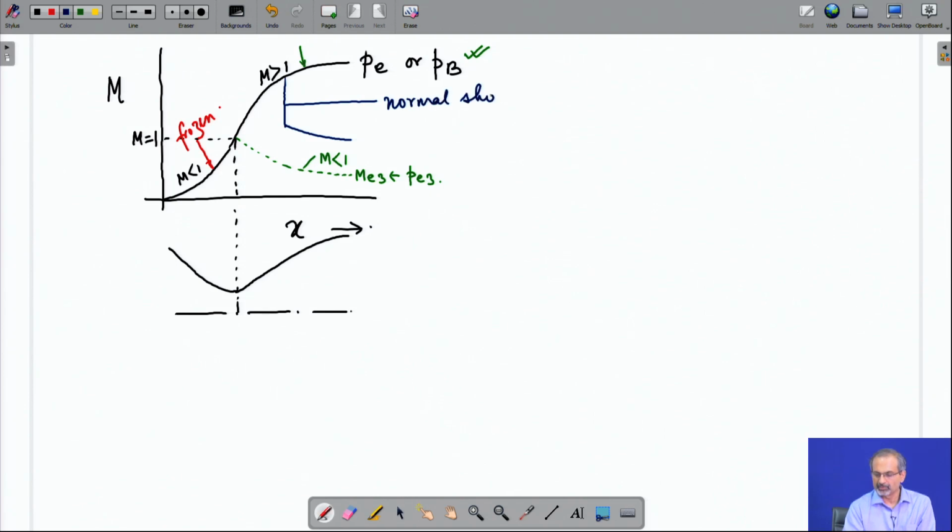A normal shock may be formed in the diverging part of the nozzle, here in the nozzle, and the moment it happens, you have a subsonic flow and you are giving it an increasing area, and therefore, it will slow down further, and that is how the Mach number keeps decreasing till it reaches the exit if you are increasing the area.